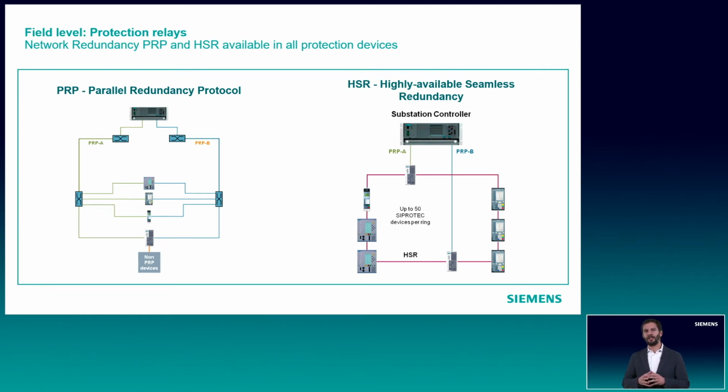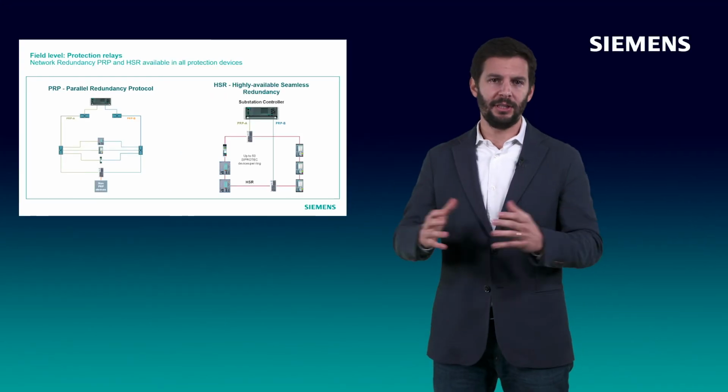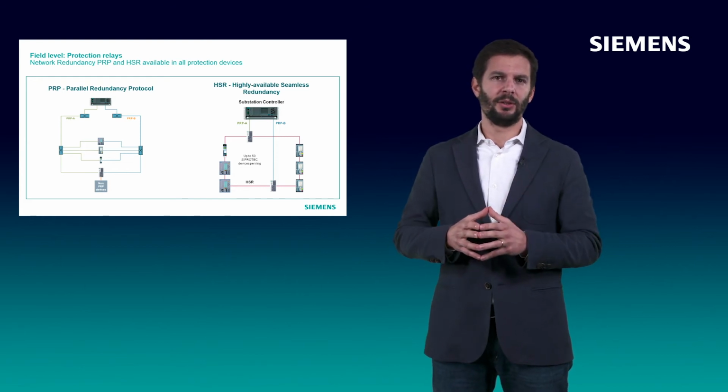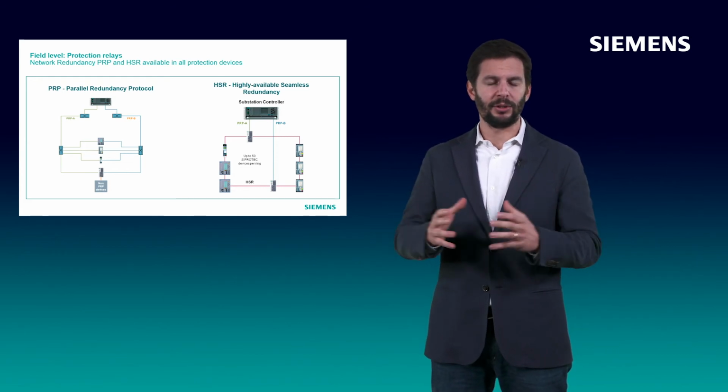But redundancy is not limited to the protection itself. Network redundancy is also a very relevant topic when it comes to the deployment of mission-critical applications such as load shedding or generation control. The use of IEC 61850 as a state-of-the-art standard in substations often combines the traditional SCADA requirements of reporting and control along with protection signaling for blocking and permissive signals. This protection signaling will use GOOSE messaging, which can be published over the same SCADA network.